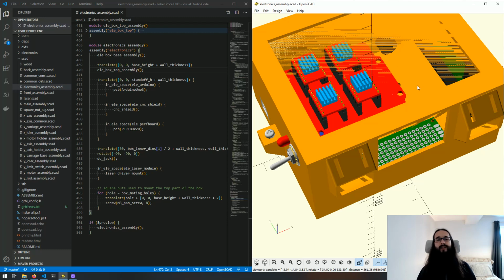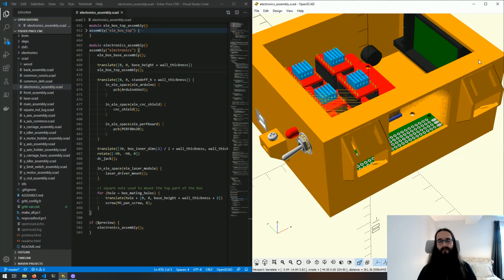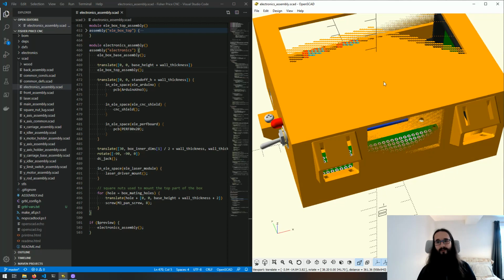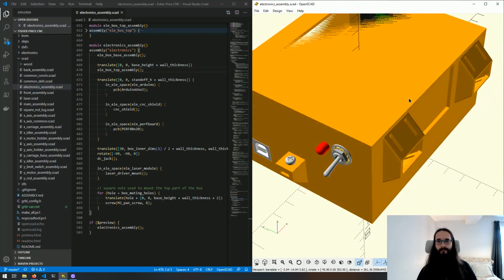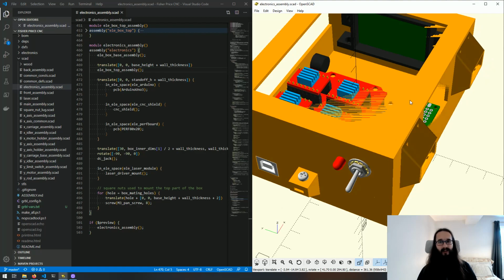and what I might want to do is figure out what exactly is going wrong there, and I want to design a driver board or something to sit in between this Arduino and the driver board to make sure that the laser can only be turned on by a deliberate high signal from the CNC shield Arduino type thing. Because I don't want to accidentally burn the house down.